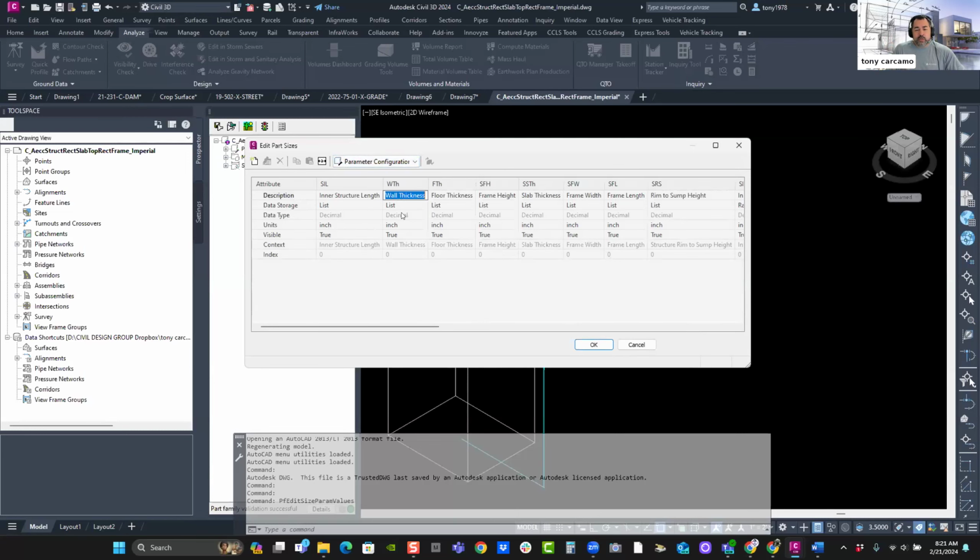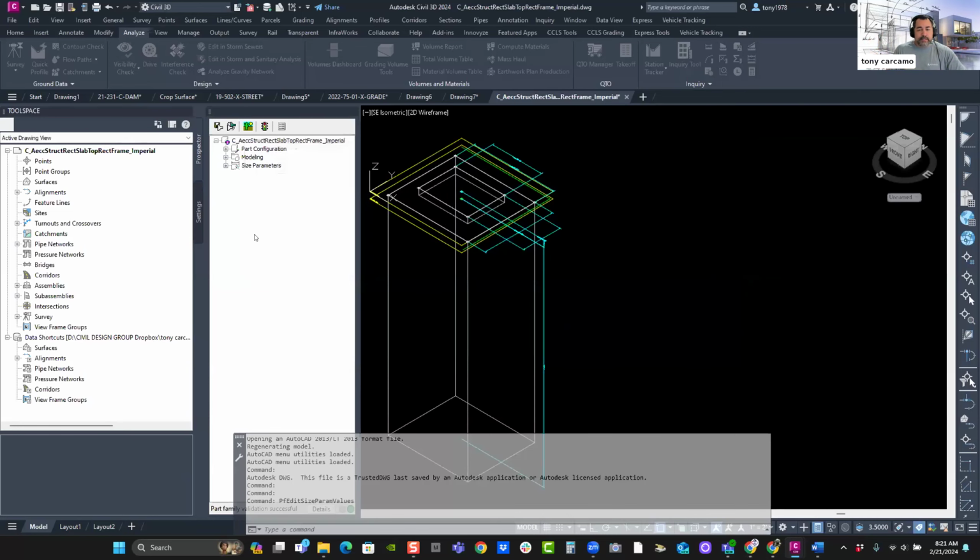So let's say I do walls and I do a table. Now, table means you're going to actually create a table based on the wall thickness and the diameter. It's something you're probably getting from the manufacturer. I don't do this too often. Most of the time I give it a range or I give it a list. But yes, you can do a table for wall thickness. Let's go look at the values.